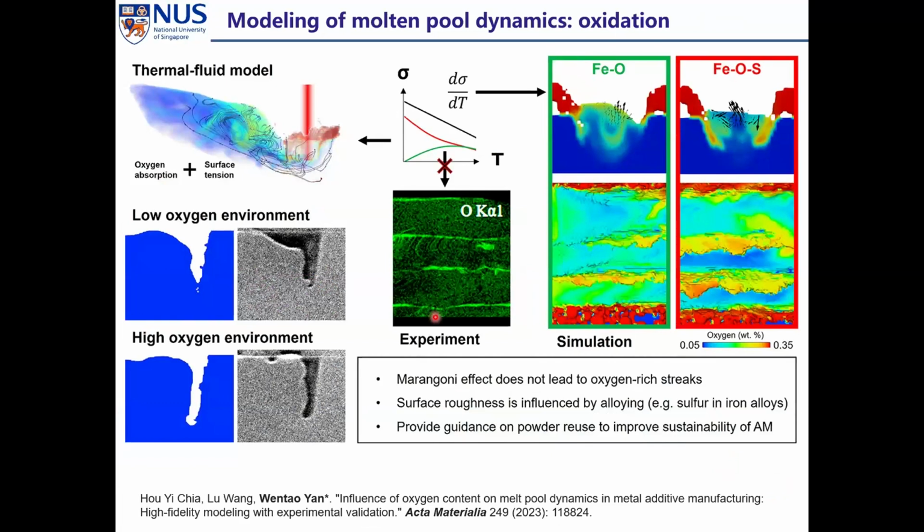Essentially, this model is widely applicable to different gas-liquid reactions, and we just consider oxidation here. So we consider the different locations will have different temperature, different chemical combinations. So the oxidation rate will be different. And also there are some initial oxides in the material. So these oxides from the original one and also the oxidized one, they will redistribute along this melt pool flow, and then in turn they will influence the surface tension coefficients. Then in turn they will influence the melt pool flow.